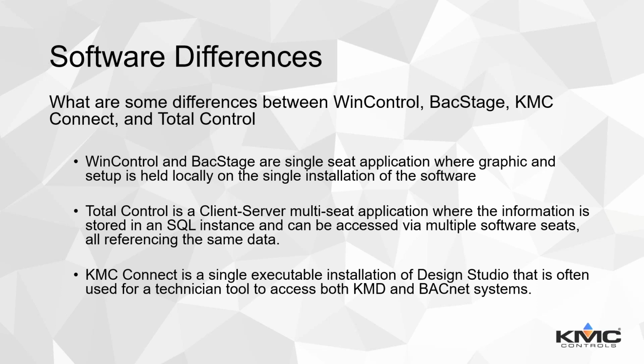When you set up a graphic on the machine, you set up that system group, and on your machine, you're going to have a file that specifies the XY coordinates. So anybody that's worked with WinControl before, and you've come in and tried to look at a graphical page and you don't see it laid out on top of anything, everything's just kind of pushed up into the upper corner. That's because you don't have the graphical file on your machine that specifies where those go.